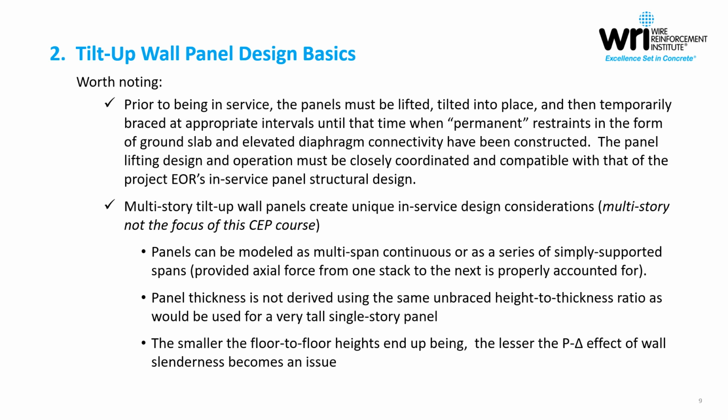With multi-story tilt-up wall panels, again, this is not a focus of this particular course, but there are some unique in-service design considerations. Panels can be modeled as multi-span continuous sections or as a series of simply supported spans. If you do the latter, you need to make sure that your axial force from one stack to the next is properly accounted for.